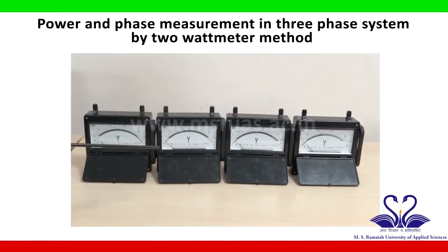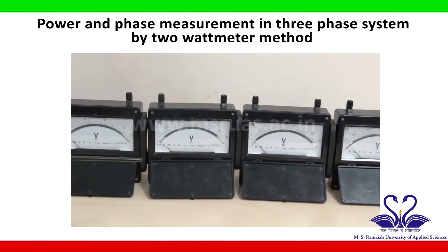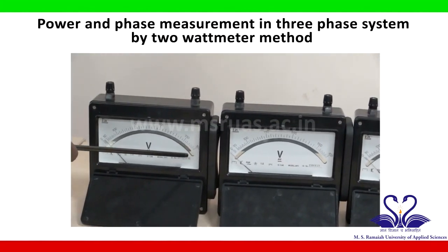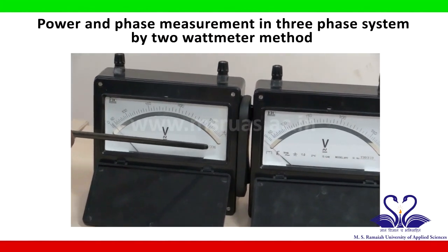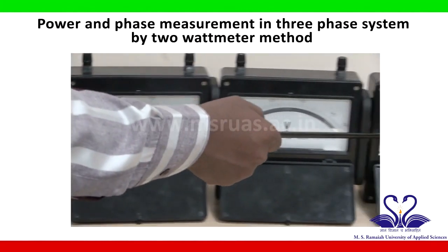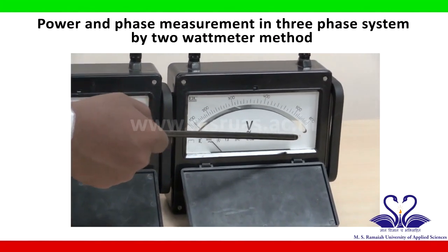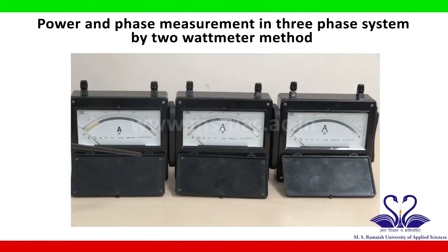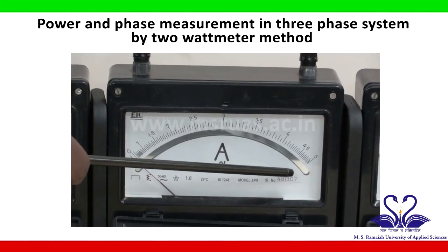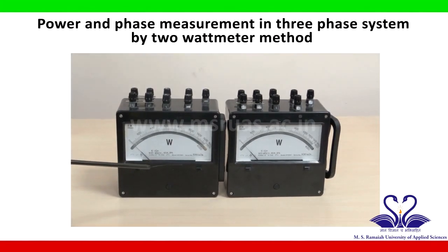We need 4 voltmeters to measure the voltage. Out of 4 voltmeters, 3 voltmeters should have the rating of 0 to 300 volts, and 1 voltmeter should have the rating of 0 to 600 volts. We need 3 ammeters with 0 to 5 amperes rating to measure the current in a 3-phase system. We need 2 wattmeters to measure the power in a 3-phase system.